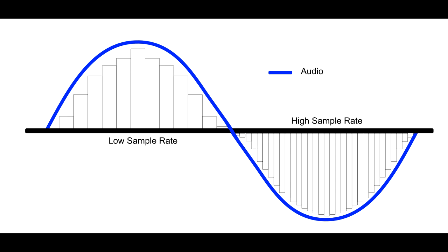When collecting data by means of an analog to digital converter, the data will be stored and displayed as a series of voltages corresponding to the information being sampled. If one does not properly select a sample rate, the data collected may show trends that are incorrect.